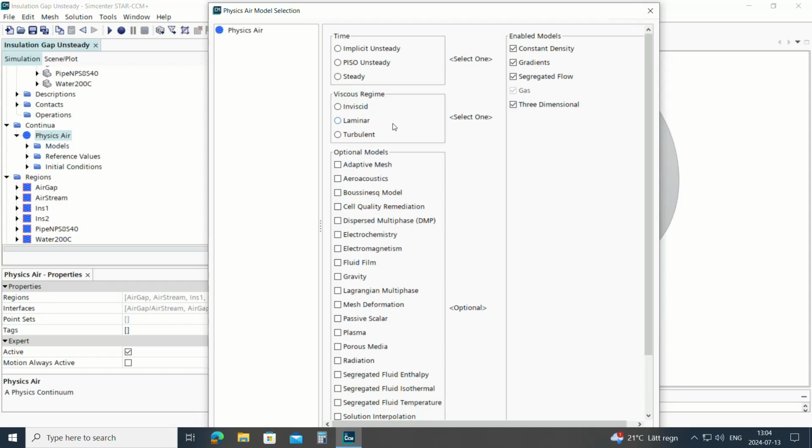In that condition, the internal surface of the pipe will be at constant temperature, same as that of liquid. Okay, so by having such an isothermal condition, we can do a steady state simulation to find the initial temperatures for pipe, water column, as well as the insulations. Okay, and using that initial temperature condition, we can then do the unsteady simulation. Okay, so that's how we are going to do.